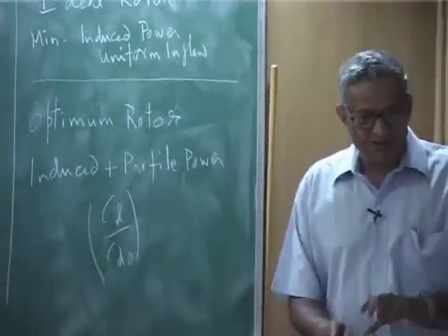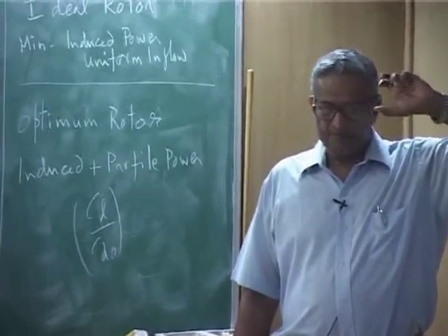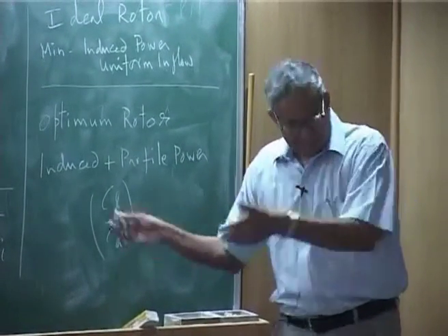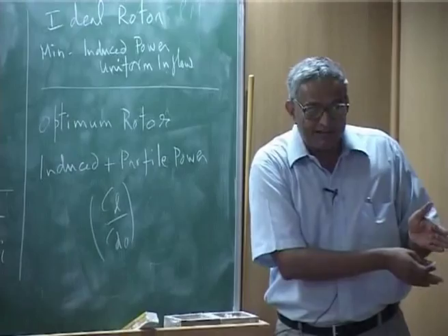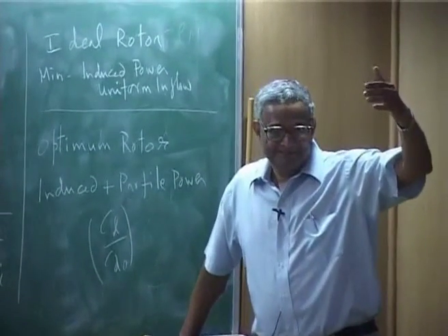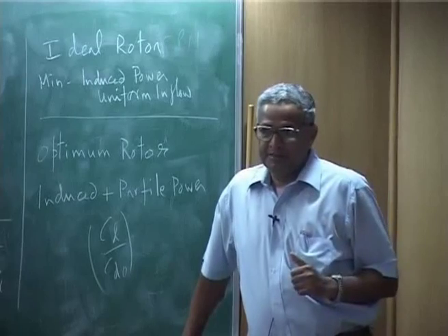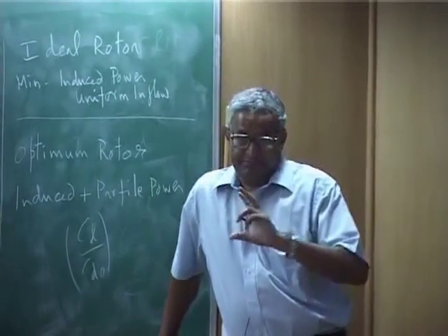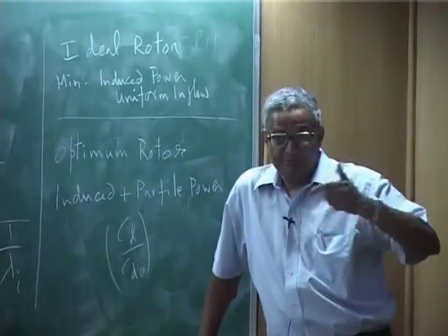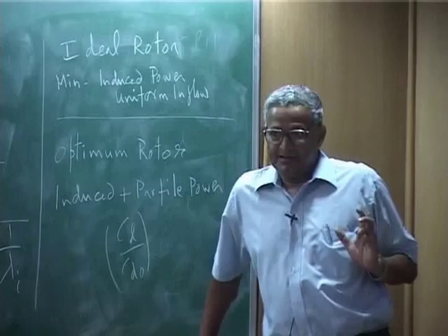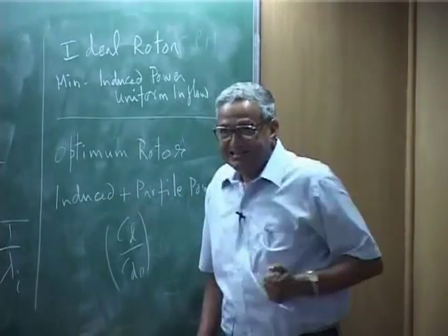If you have this quantity more, then I am reducing my CD naught, that is the profile drag is coming down, and my CL is also high. Now this is an airfoil, so what is the angle of attack, because Mach number and all those things will come into picture in the real rotors.